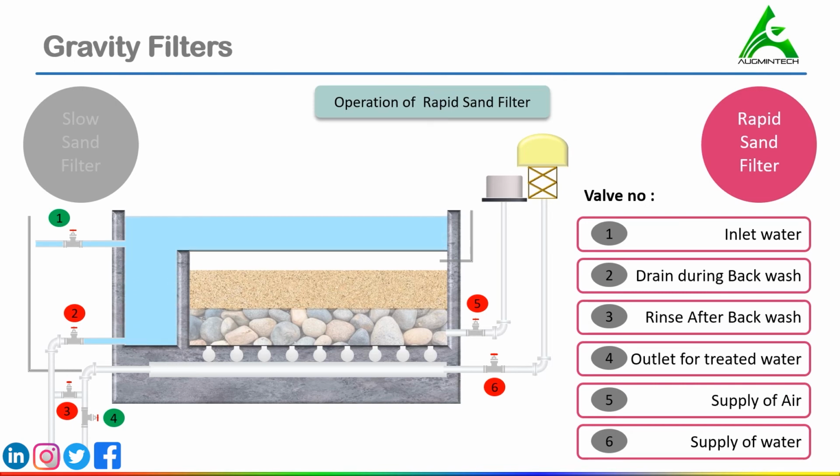With the help of gravity force, it passes through the filter medium, that is granular sand, and after that filtered water moves to the lateral drains passing through the layers of gravels, and from these laterals waters are collected into the central drains, which further moves for the storage following the disinfection process.